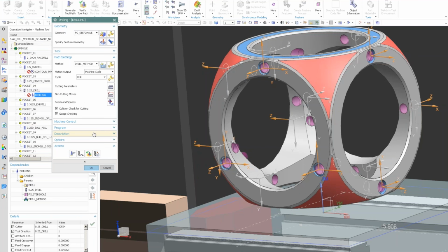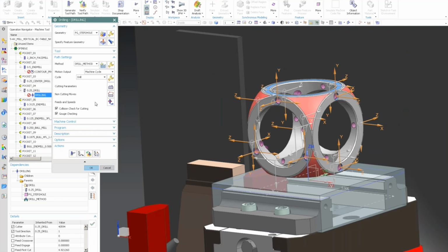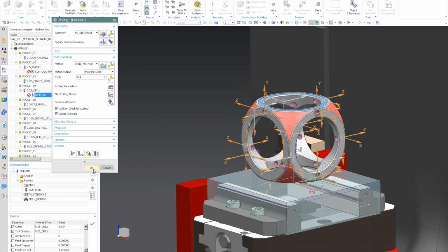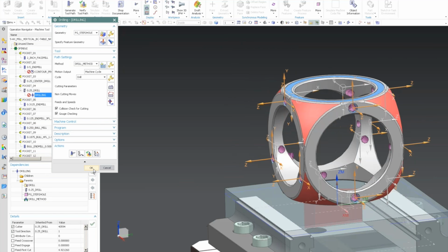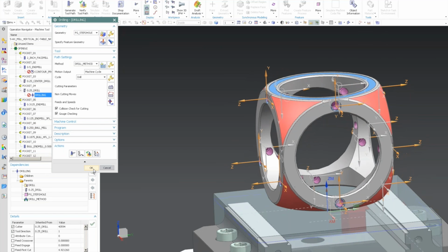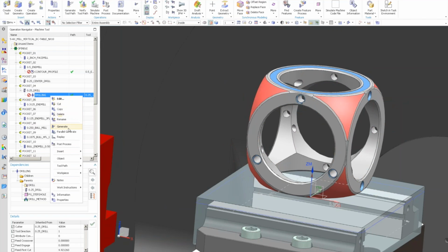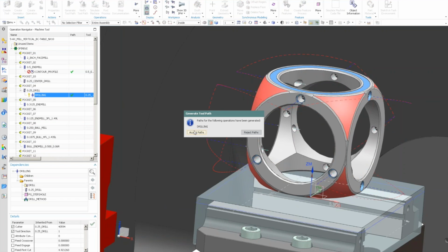One thing we find, we've had to do some deep hole drilling, even interrupted holes, and that's all kind of built into NX, where you can have it go into a pilot hole and turn up the RPM. Once it goes into the pilot hole, it recognizes where the material is, goes to the bottom of the hole, and then stops the spindle and pulls out.